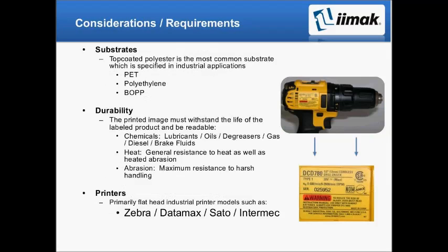The type of substrate and the durability requirements determine the label solution. Another element is the TTR ribbon, and we'll of course cover this later. Durable polyester labels are the most common substrate for industrial applications. They can be top-coated or corona treated for enhanced TTR printing.